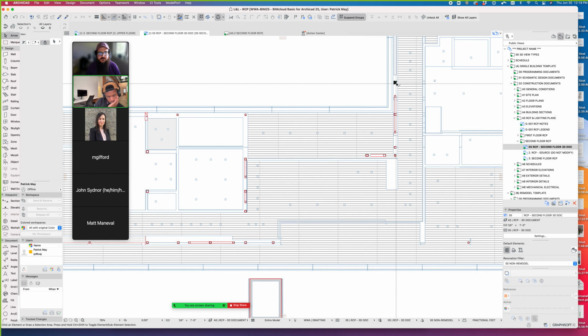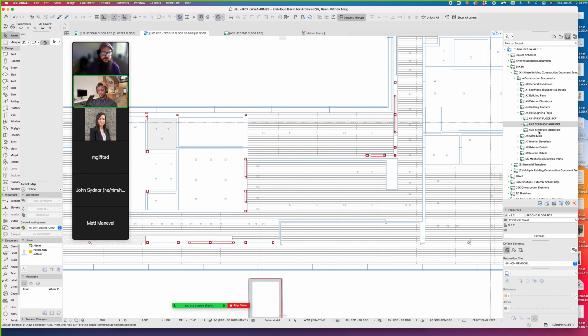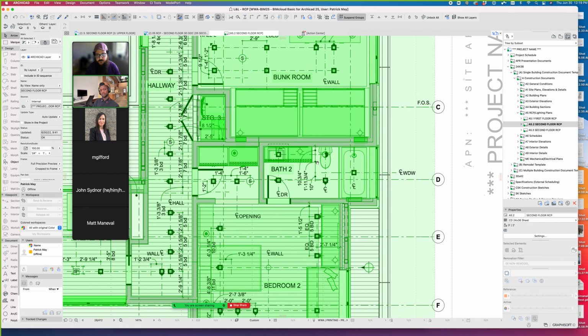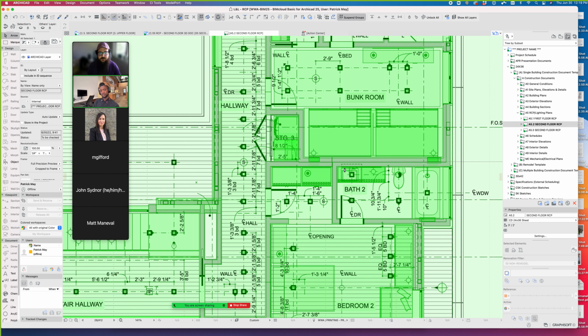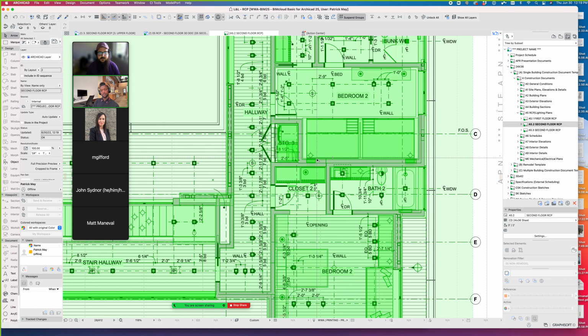The other thing that I've done in the template right now is I'm showing the column layer on both the 3D document and the floor plan. That also gives me a way to make sure that on that layout, when those things get dropped into the layout, that those line up. So I can actually physically line up that column from the floor plan to the 3D document and verify that those two things line up, because we're not showing walls and we're not showing actual cut elements for the most part in the 3D document. So that allows us to line those things up.